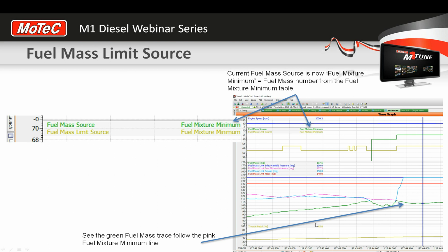Now I know that doesn't do the maths right with the pedal, but our pedal isn't linear. Our pedal might be at 45%, but we could have a linearization number of 80 or even 100%. So 45 can equal 80% of the main. So the whole intention of the pedal table, which is called the nominal table, is to allow you to linearize the power, or have the power come on any way you like, proportional to where the driver has the pedal. Alright, so that's what's working out there.